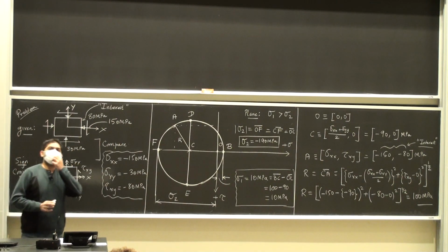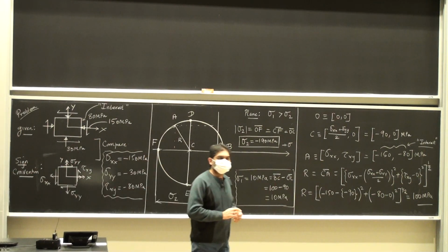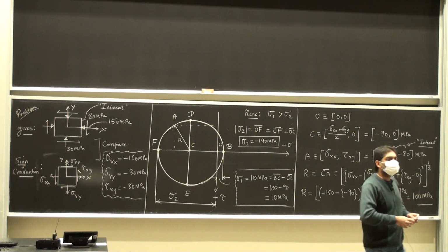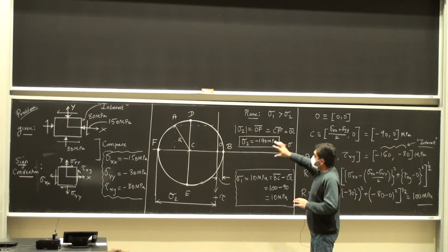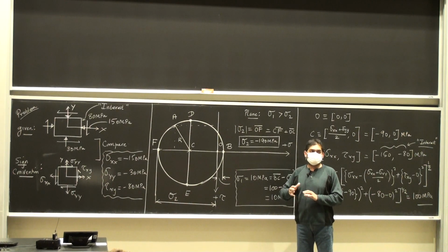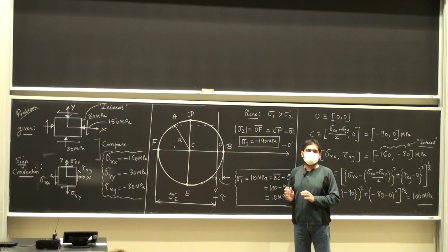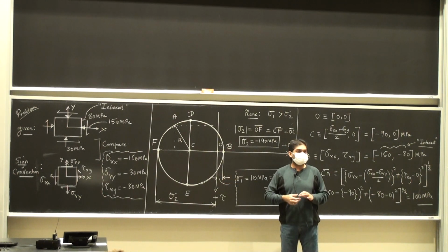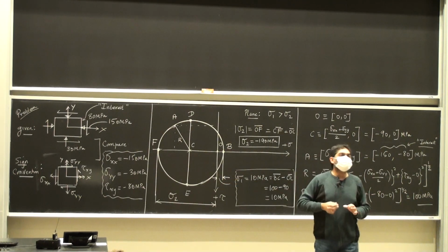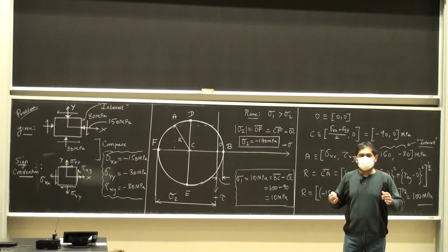Maybe I'll give a brief pause here and see if there are any questions. Yes? I was watching a video, and they gave the formula to find the stresses as sigma average plus R, and for sigma 2, sigma average minus R. Your choice to use it. I would always go with the figure, because that is more of an understanding. It says that this is just a distance, and all I need to do is calculate that value there. Yeah, it considers the distance between the origin and the principal stress and just adds the radius to it. You can do it that way.